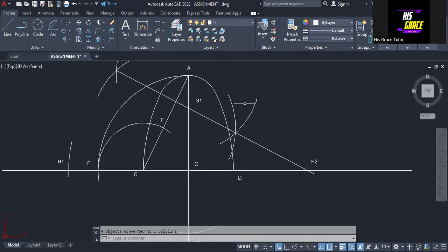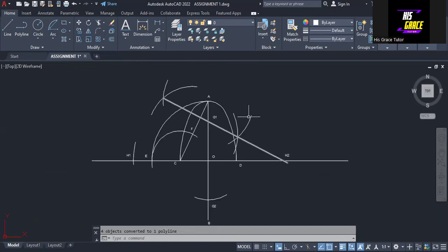All right, so we are now going to mirror the whole of this so that we can have it down here. So how do we do that? I will click on mirror. Okay, select the object to mirror. Then I will right click. Then I will click on this horizontal line. So it comes like this. Okay, so take it easy to this point. Okay, so we have it like this. So click on select no. All right, so we have it like this now.